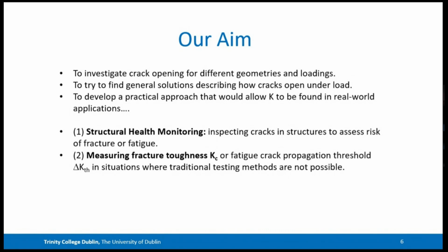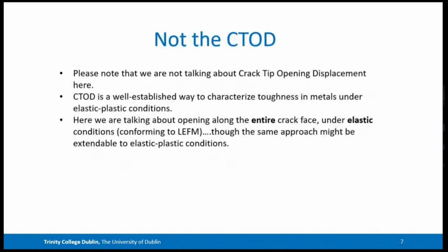Just a point, because some of you might have thought of it, this is not the CTOD. Crack tip opening displacement is a well-known way of characterizing toughness in tough materials, usually metals, but we're not talking about that. We're talking about an elastic, essentially LEFM kind of conditions, and we're talking about the elastic opening of the entire crack face from mouth to tip, rather than just the opening around the tip.